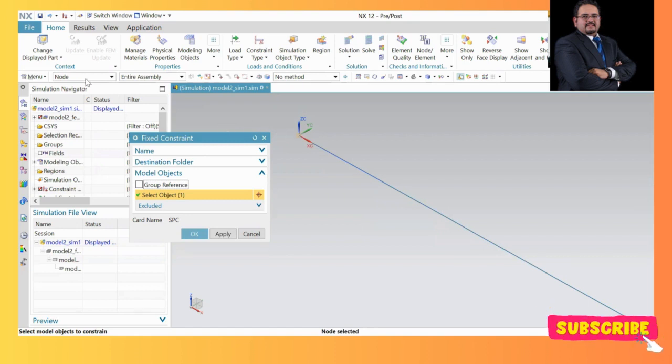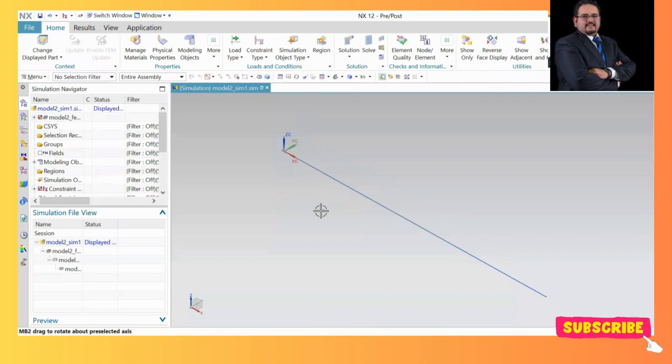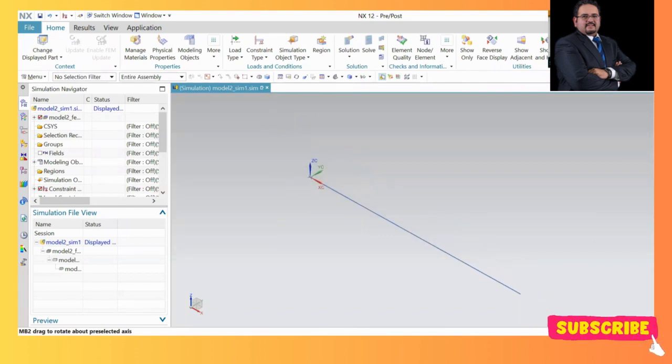Make sure that your filter is node, so you can easily pick node, right? Otherwise, when you come near, there are many things, it can pick line as well, right? So in order to have the right selection, you make sure that you pick the node. So I fixed the node, and now I am going to apply force here in Z direction, right?